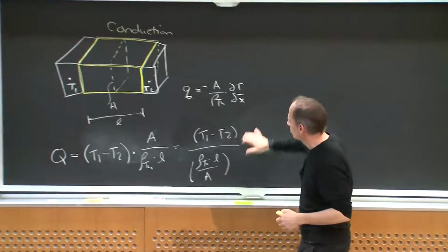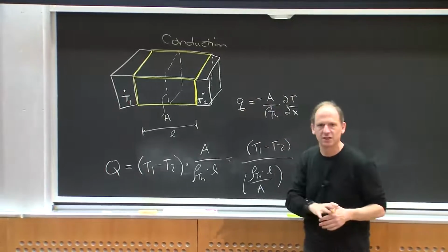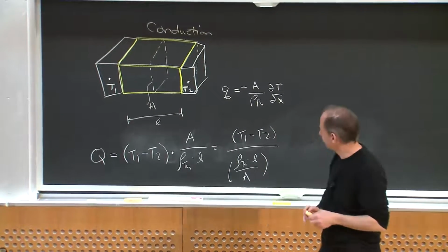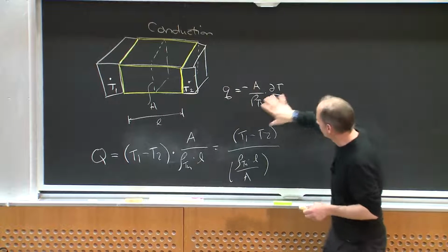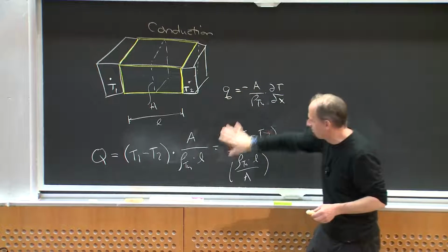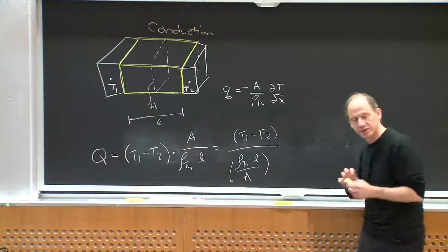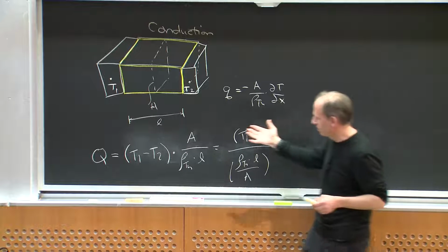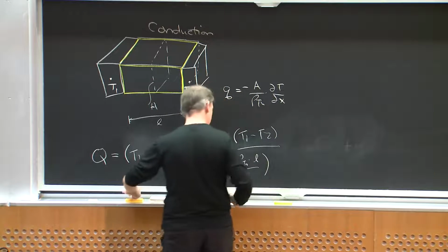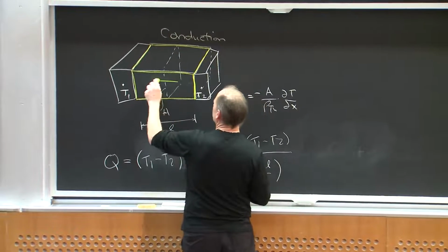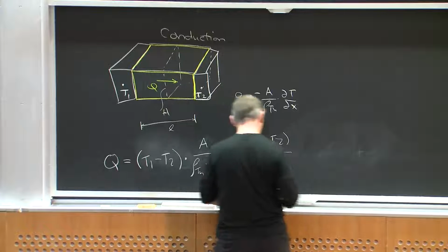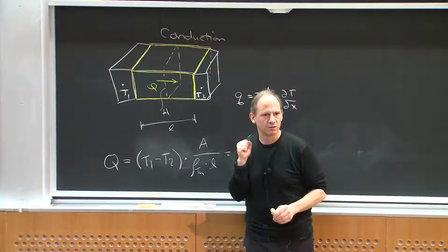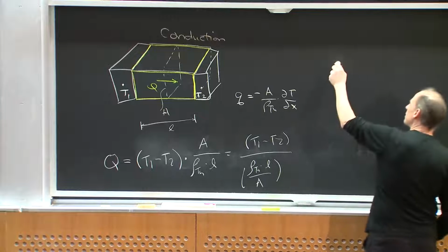And if I want to start doing Fourier heat transfer, I get into these kind of differential equation descriptions. But for a bulk piece of element, we can write it like this. Okay, this relationship where Q is my heat flow, right? So Q is whatever heat's flowing this way. Okay, sort of suggests a circuit analog, right? Where here's my circuit model.